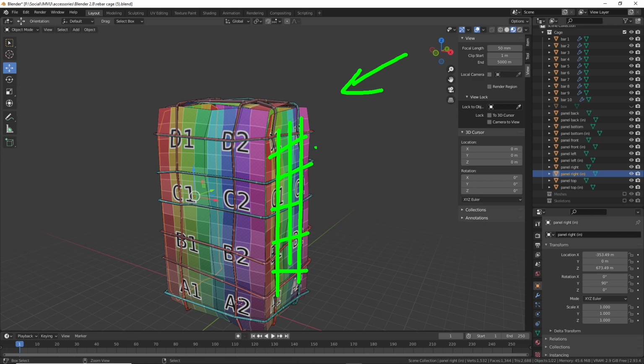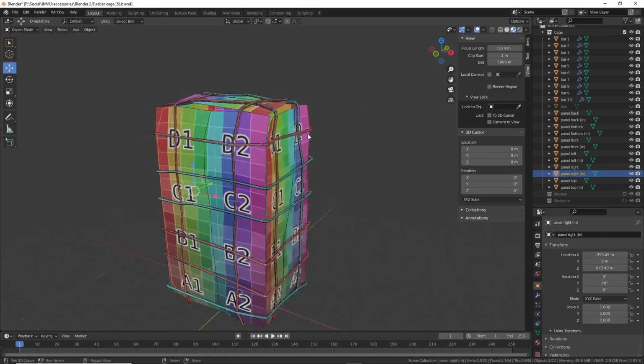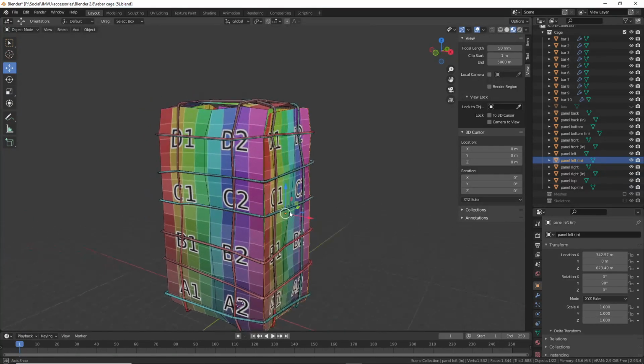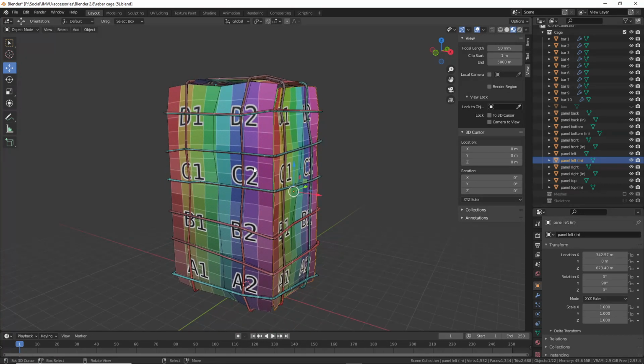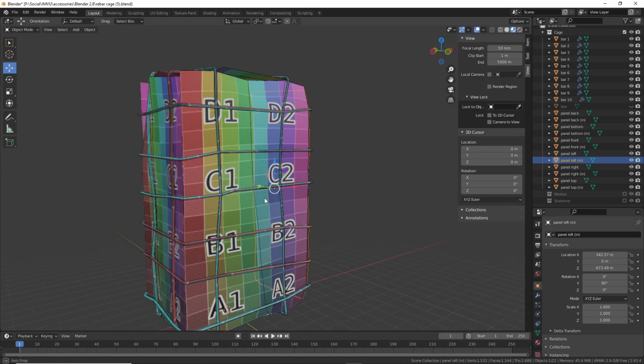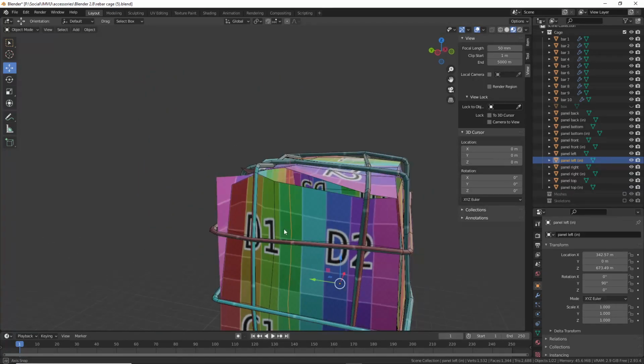When it does that, it means that the normal map that's then on the inside of the mesh is still reacting to the lighting that's on the outside of the mesh. So to compensate for that, we have to duplicate the mesh and invert a face or a section of it, whether it's a part or whole, so that it reacts correctly to the lighting. We'll see this once we get this all sorted out. Right, so that's that prep work done. So that's just the basics.